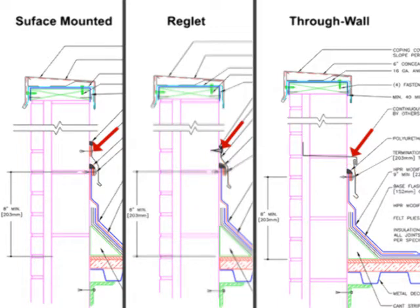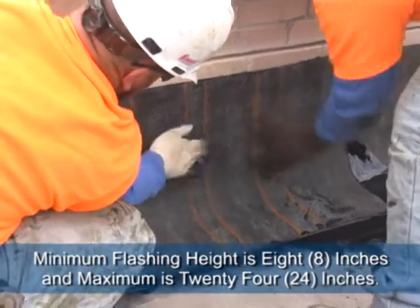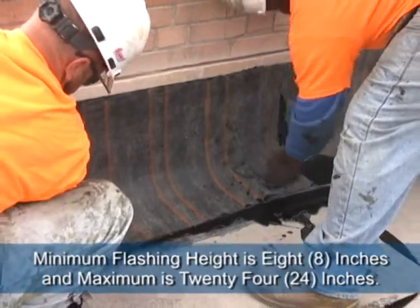As attachment of the counterflashing may vary with both the riglet and through-wall details based on the construction material of the wall, it is important to review the project conditions with your local Garland representative. Minimum flashing height is 8 inches and maximum is 24 inches.